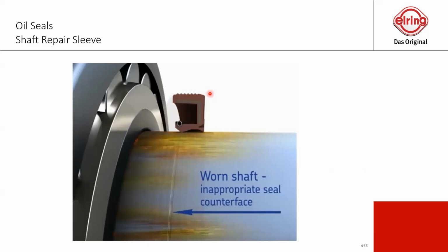It's more like pushing metal to the left and to the right. So if you install a new ring on the same spot, it gets difficult because the diameter of the shaft is getting smaller. You should avoid putting it directly on the same spot. It's recommended to put the oil seal further inside or further outside.